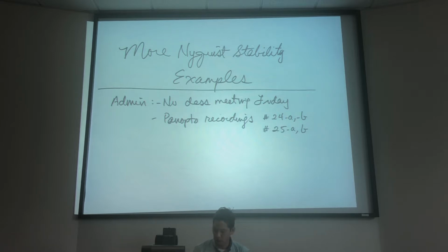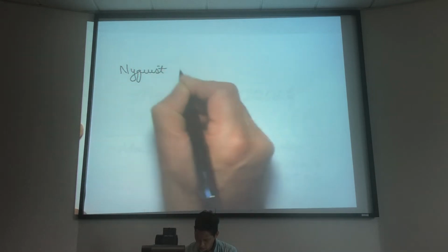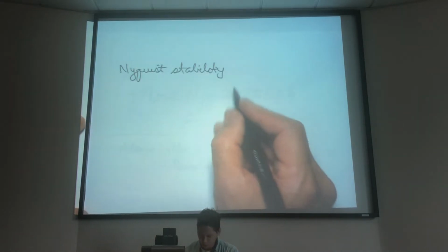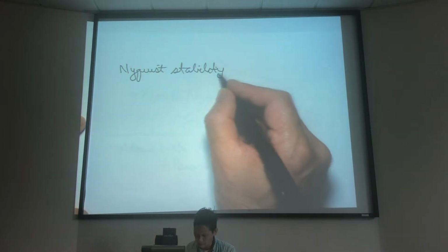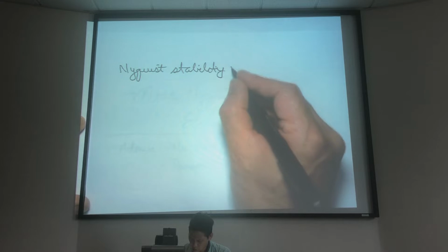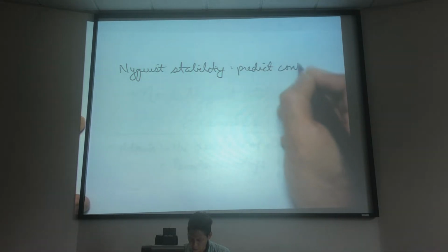Today, what I want to do is go over a couple of Nyquist stability examples, and let me first review this technique. With Nyquist stability, this technique allows us to predict control system stability.